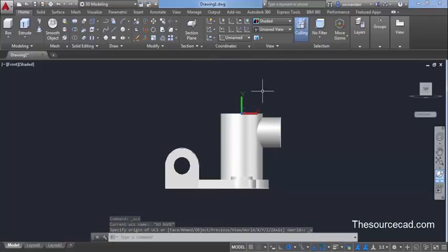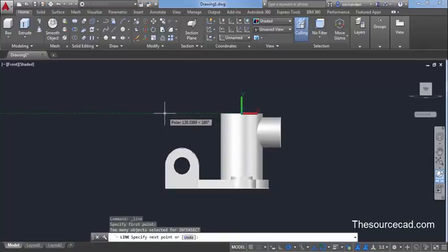Make sure that you always make your drawing in XY plane, because a drawing cannot be made in any other plane in AutoCAD. So now we have reached this XY plane. Let's start making our geometry. So I'll start with a line command and select this center point. Now make a line. So drag your cursor towards this left side of your geometry and enter a length of 35 units. So 35 and press enter.